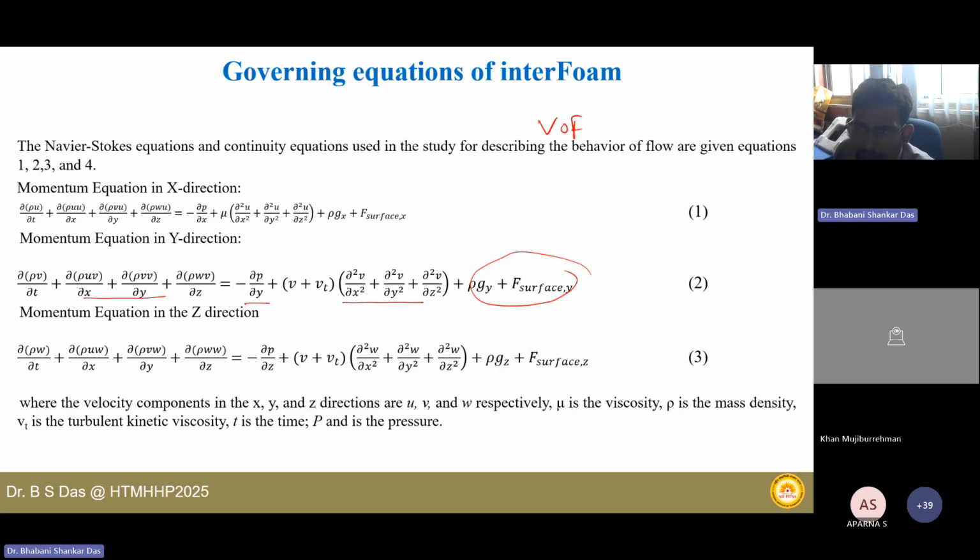The convective term is basically convection. It means the fluid is flowing. Water is flowing, and that can be handled by a convection equation, a first order differential equation. Advection is a subset of convection. If the fluid is moving along with some sediments, then that will be considered an advection equation. Some extra terms will be introduced in those convective equations for the sediments, or in a pollutant transport problem, the pollutant in an airflow, that is an advection problem.